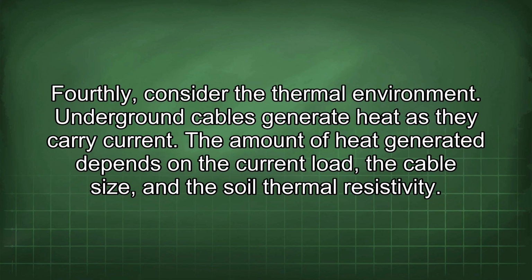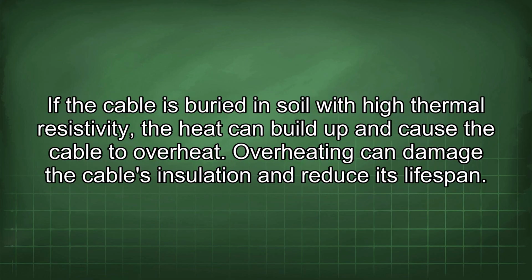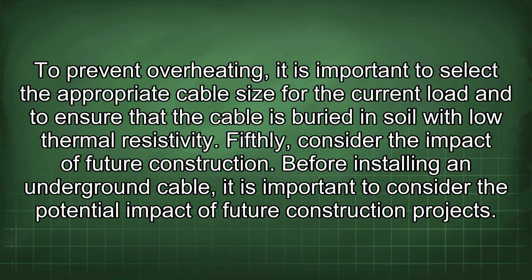Fourthly, consider the thermal environment. Underground cables generate heat as they carry current. The amount of heat generated depends on the current load, the cable size, and the soil thermal resistivity. If the cable is buried in soil with high thermal resistivity, the heat can build up and cause the cable to overheat. Overheating can damage the cable's insulation and reduce its lifespan. To prevent overheating, it is important to select the appropriate cable size for the current load and to ensure that the cable is buried in soil with low thermal resistivity.